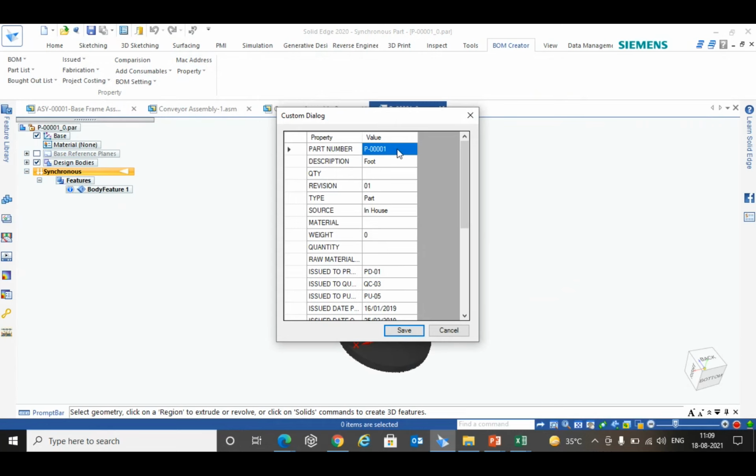Vignesh, there's one more question from Mr. Kushal. He wanted to know if an existing bill of material can be modified. What I understand is that what you are presently showing on screen is the way to modify the details. Yes. Let's say you want to manage the revision of this bill of material; that can also be done. Let's say I prepare some bill of material today, and some modification happens after 5 or 10 days, and I need to recreate the BOM after this modification. You will then get a new version of your bill of material.